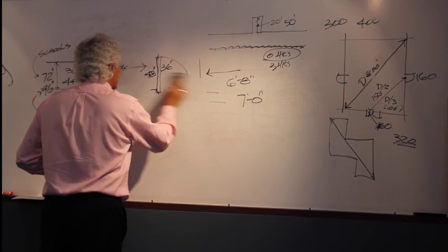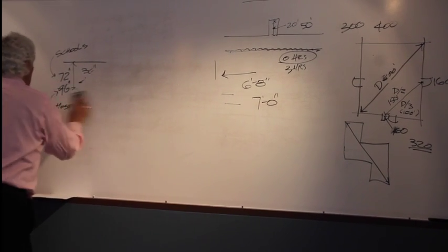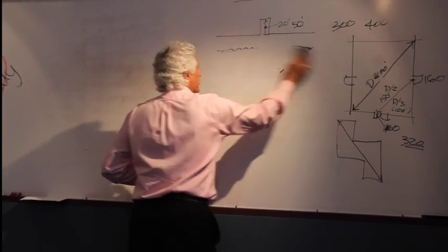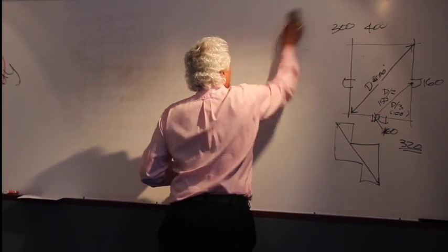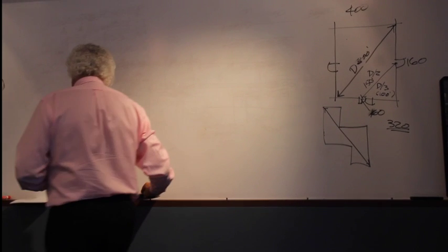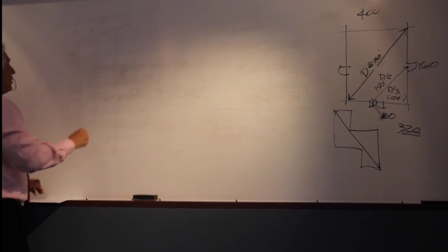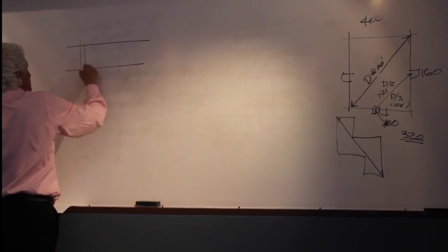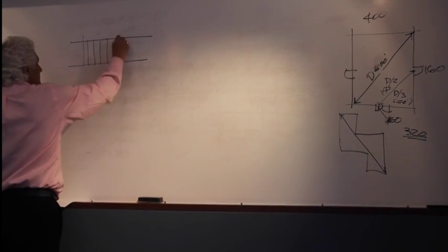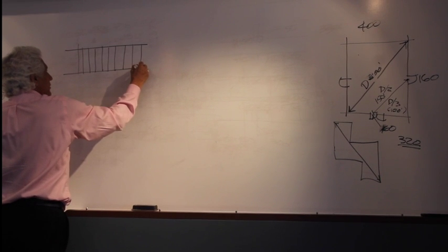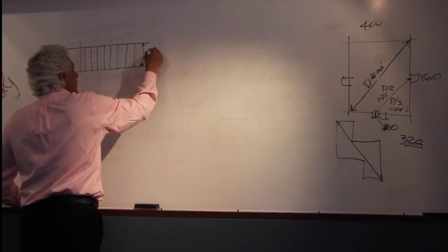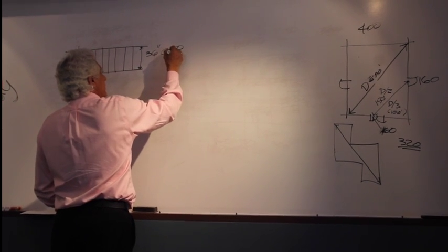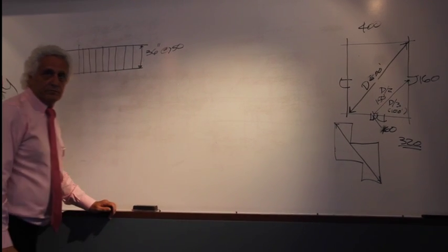Another one that is a little bit of a mystery to us in the beginning are stairs. Stairs are different for residential versus the non-residential requirements. The stairs require a minimum, like corridors, of 36 inches wide if less than 50 people.